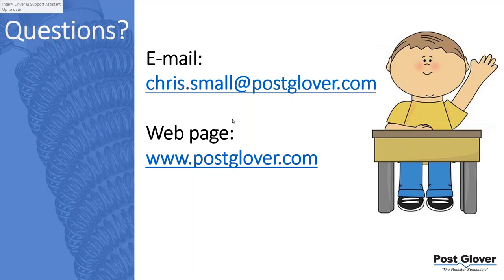I'm going to hijack a question that was asked by a longtime listener, first-time caller, Bill. He's asking what type of HRG is recommended on a 480-volt wall-mounted power panel fed by a specific transformer. What I'm going to rephrase to Bill, if you'll permit me, is: is the HRG size based on the transformer that's feeding that system? So the answer is no.